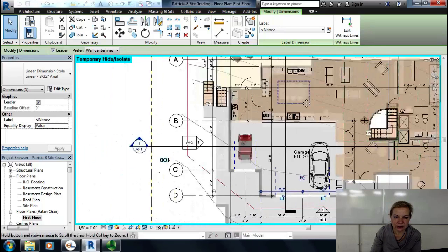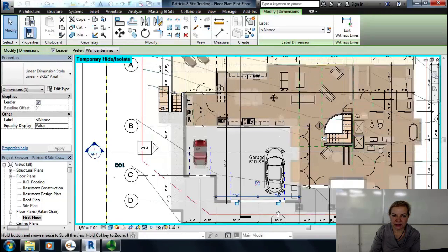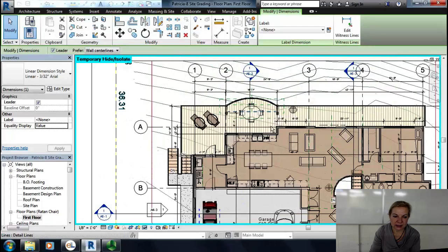So the interior strings, you should have enough of them laid out nice and clear that you will clearly cover the most important locations of walls. The jog in the kitchen belongs on the outside, so the outside string will show the jogs. I have the grid, so my jog is from center line to center line of the bearing structure of the wall, and that's where I place the grid.